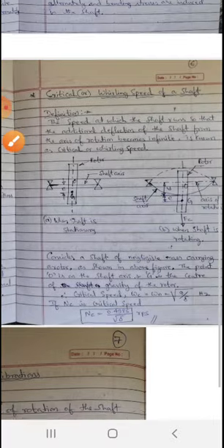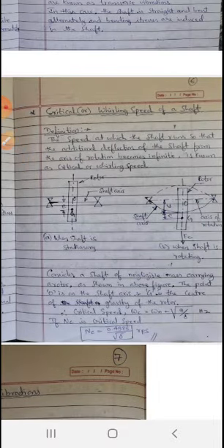For what purpose are we going to study whirling? That means the reasons for whirling. I would like to say about the reasons of whirling. First one, eccentricity, that means the distance between the center of gravity of the gear or pulleys and the axis of rotation. The second thing, the speed at which the shaft rotates. And third, bending due to its own weight in case of a horizontal shaft.